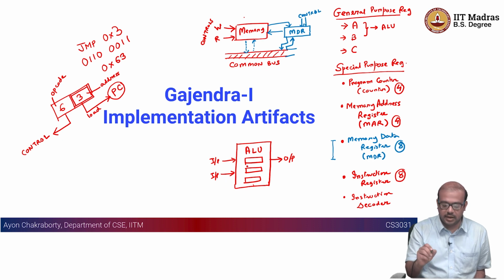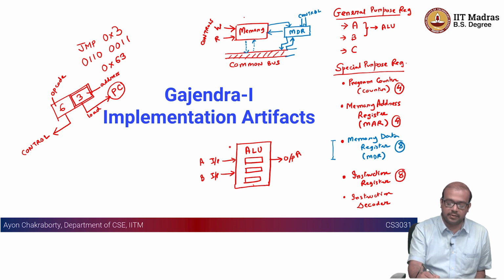Again, in our case, there could be 3 registers also: source 1, source 2, destination 1. Here we were assuming only 2, A and B, and in most cases the result was written back to A. So the result output is written back to A, and here you have some bits that are dedicated to the type of operation.